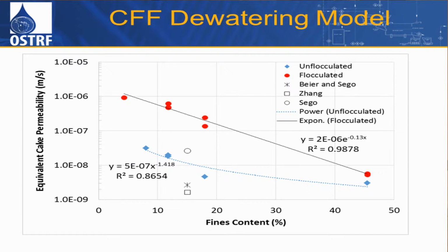And so now, to develop the dewatering model, I calculated an equivalent cake permeability, and I used that to estimate the filtration surface area that we needed for our Crosswell filtration process. When you take into account the properties of our tailings and the filter medium, in the original work that we did, we were just trying to see if it would work. We weren't really working on optimizing the process, but if we were to calculate the surface area that we need for that low permeability, it would be like 60,000 square meters. So it's unfeasible at that filtration rate.